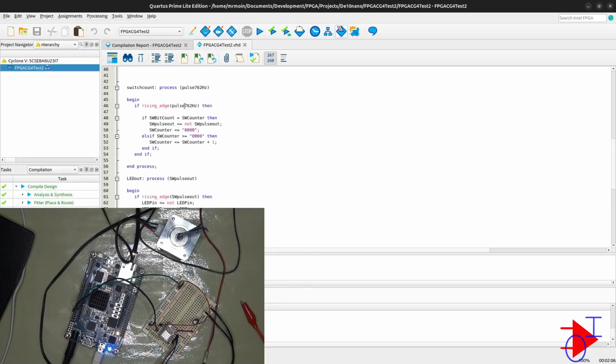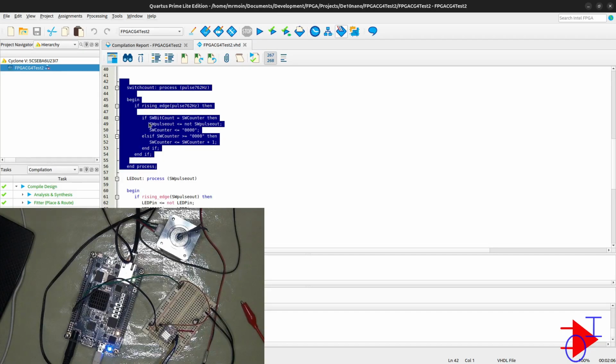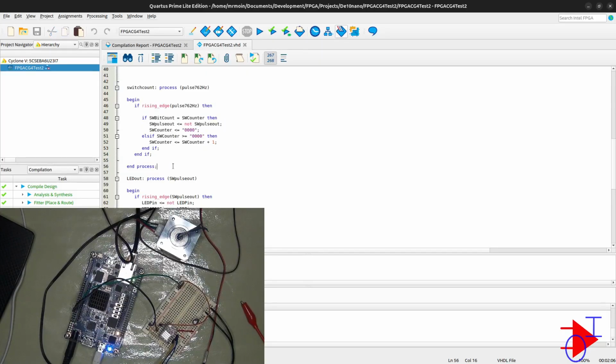join that 4-bit output to this process right here, where I'll create another process and keep this switch control in there. So in case we run into an issue, we can test our switch output frequency, and if that's working, then obviously we know that the HPS side isn't working. That way we can debug, in a sense. Okay, so that's basically the plan for this part.